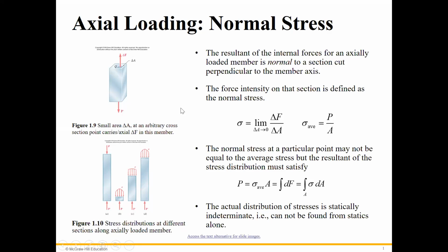Professor, will we not be integrating it at all? We'll just be using the fraction? No, you don't need to take the integral. In reality, if you have a function of the stress, then we can take the integral to get the force. But in practice, which means in this class, we already have the force from the statics. Since we have a force, we just need to divide by the cross section. For example, maybe the cross section is 2 inch by 2 inch, then the force is divided by 4 square inches.